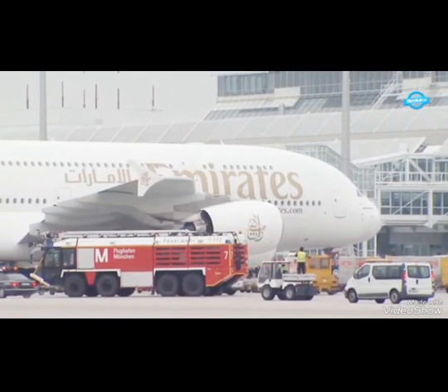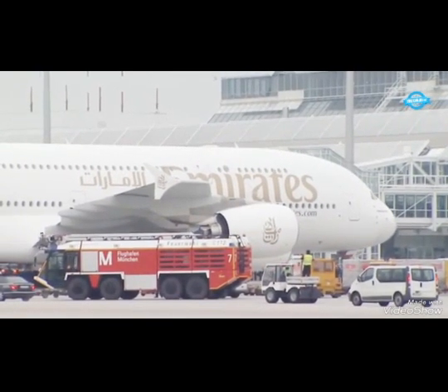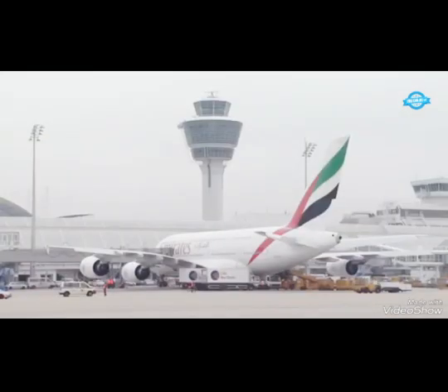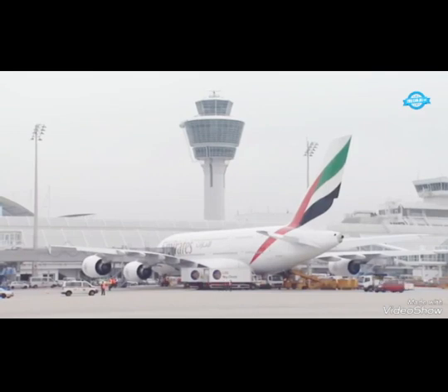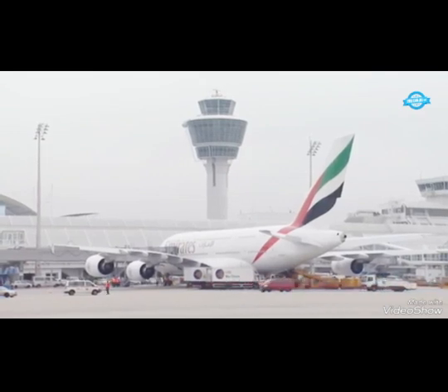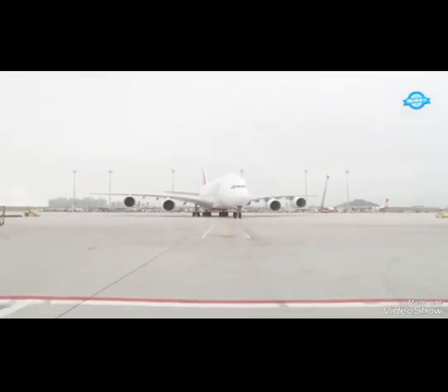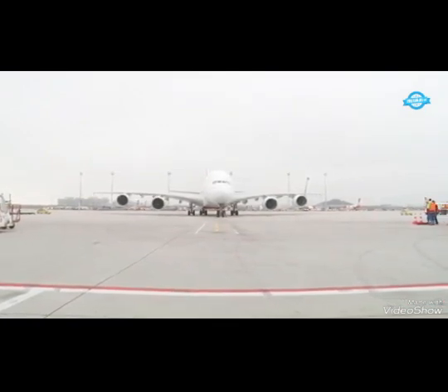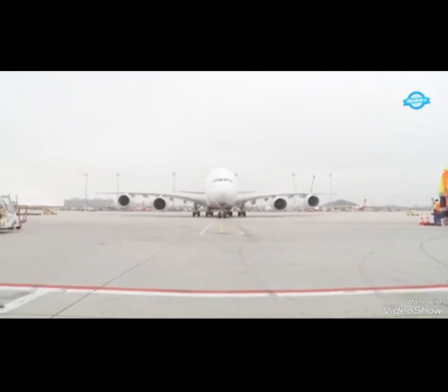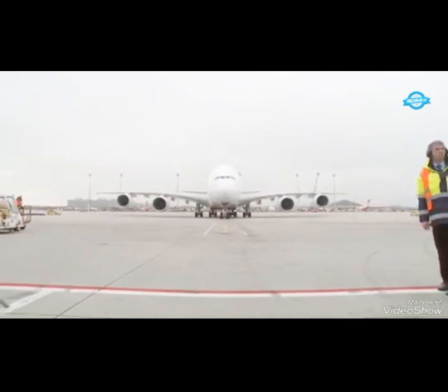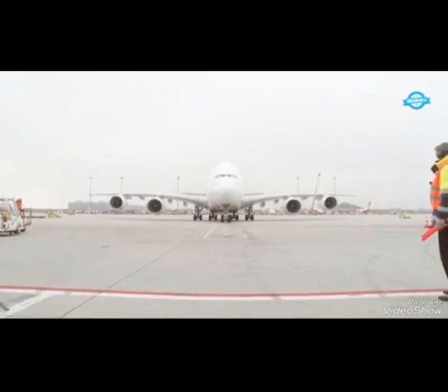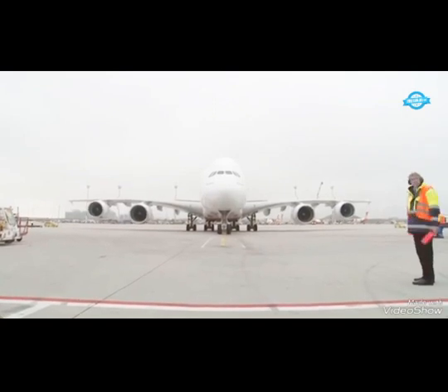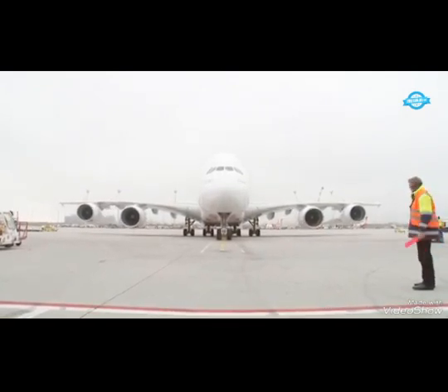When it comes to stopping the massive A380 after landing, the aircraft relies on powerful composite Honeywell brakes located on 16 of its 20 main landing gear wheels. These brakes are equipped with anti-skid technology, which automatically pulses them to prevent lockup and skidding when extreme pressure is applied. Additionally, the aircraft employs aerodynamic braking with 16 giant wingtop spoilers that rise to create drag and reduce lift. This reduction in lift allows more weight to be applied to the wheels, further enhancing the mechanical braking effect.